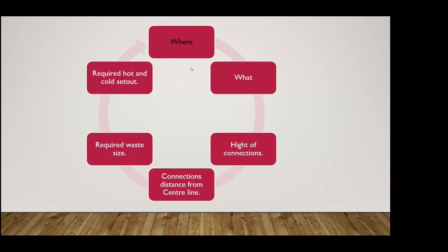But if you're doing a wall hung pedestal basin with a shroud or something, you'd ideally have it there on site, and have the trap and the plug and waste that you're going to use. So you could set it up so it was going to be bang on exactly where you want it, and the water supply was at the right height, and the flexi or whatever you used to hook it up was all going to work and look right and be nice and neat.